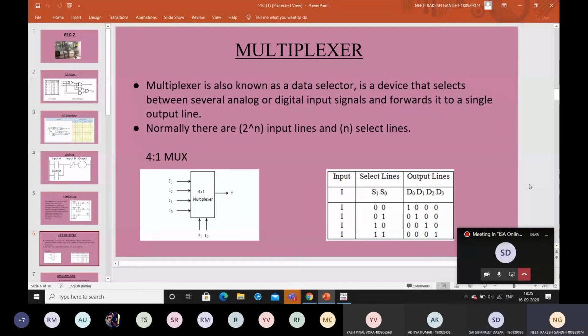So here we're going to try to implement a 4:1 mux, which is also called a 4:2 mux, because we have two select lines over here. Basically, as you might have heard in 11th and 12th standard, there are one to many and many to one functions. A mux is a many to one function because you have many inputs and you're getting one output. By this one output, I don't mean the same repetitive output. It can vary in different ways. Here my output is just one Y, but Y also has different sections of it. But I'm going to have four inputs.